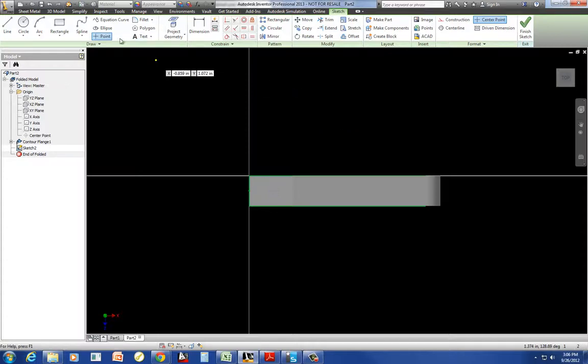The way I'm going to do that is line this up horizontally, as if I were drawing a line horizontally through this from here to that little green dot, which is a midpoint. Now I'm going to dimension it from the end at 0.156, and now it's fully constrained. It knows it's always lined up here, so if this spring actually gets really wide, there won't be a driving dimension there. This is always going to keep it in the middle. So it's a nice way to put dimensions in a sketch.